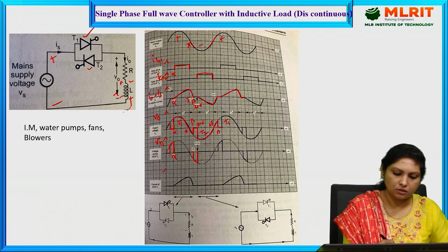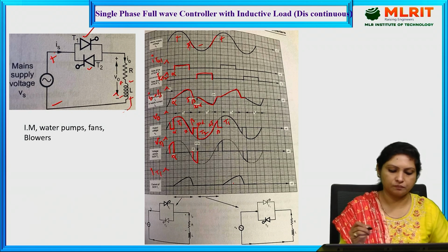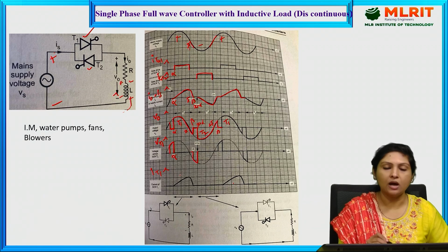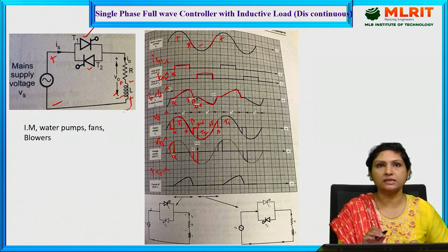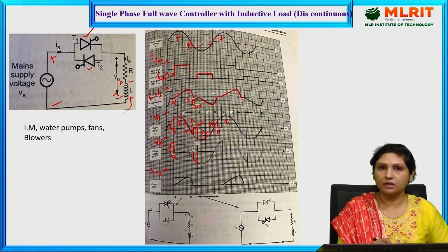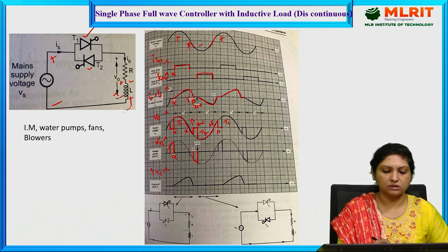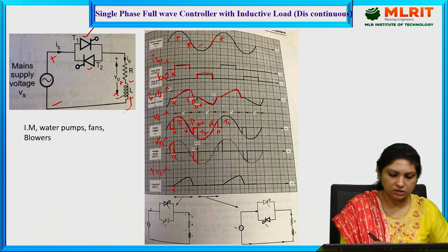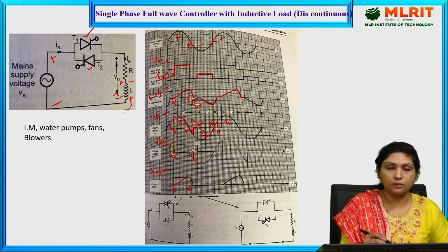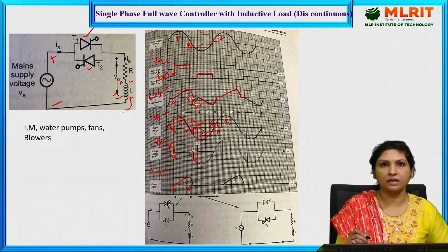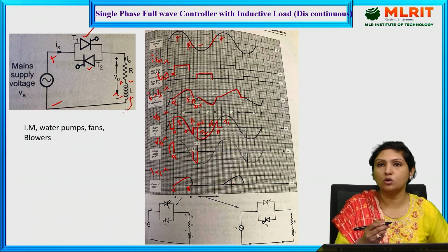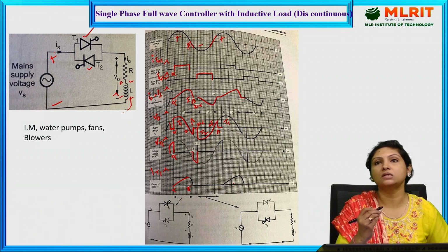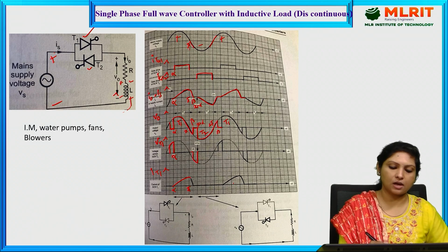And coming to the current through thyristor 1. As long as the thyristor is conducting current through the load, we get the current through the thyristor waveform. See, this is the current through thyristor 1, and it conducts right from the instant alpha, and becomes maximum at this instant pi. And the moment it reaches pi, the negative half cycle has appeared, but because of the polarities across the inductor, T1 is still maintained in conduction, and that is how it conducts beyond pi till beta.